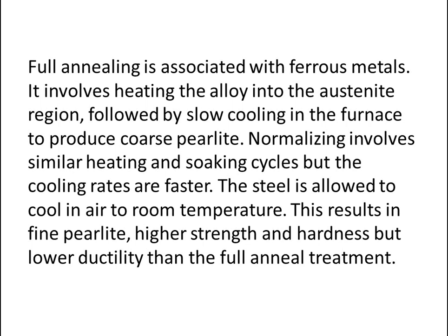Normalizing involves similar heating and soaking cycles, but the cooling rates are faster. The steel is allowed to cool in air to room temperature. This results in fine pearlite, higher strength and hardness, but on the other hand, lower ductility than the full anneal treatment.